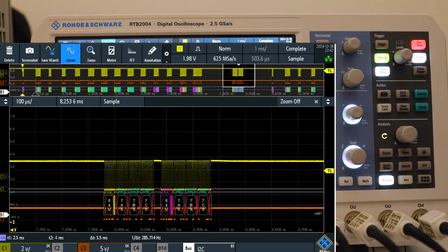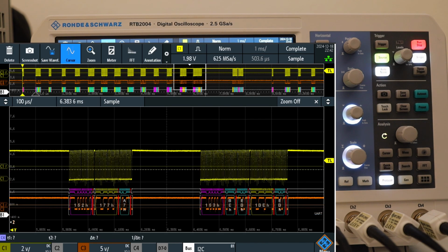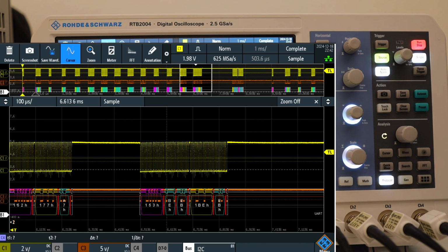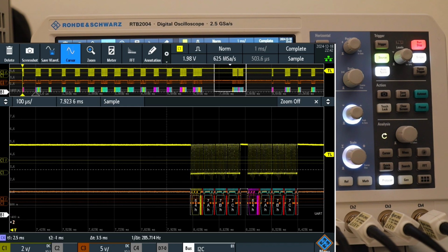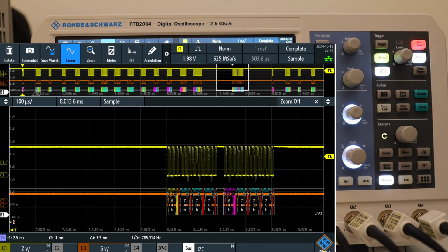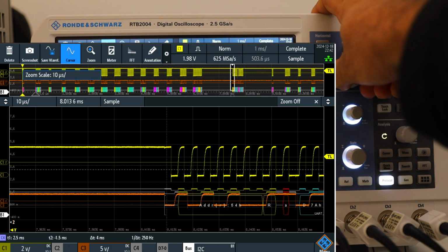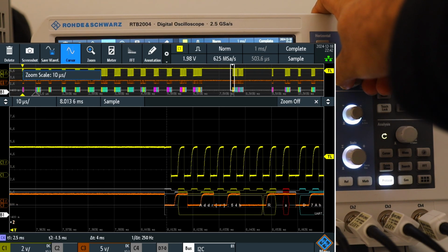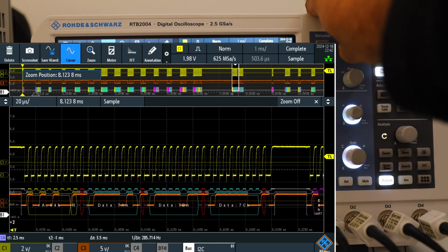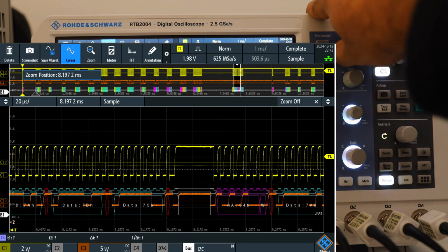So on device number 54, let's see if we have another device 54 somewhere. Okay, so this is a different thing. I do not know if it is appropriate or not. This appears to be a longer address, but we can definitely trigger on this one, 54H. First it does a read, which is represented by this yellow color, and then it does a write.